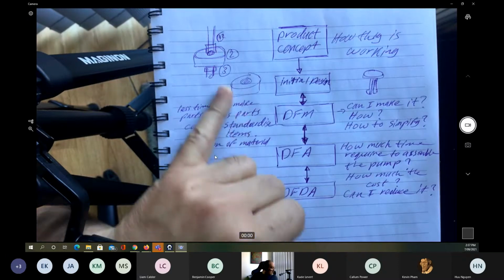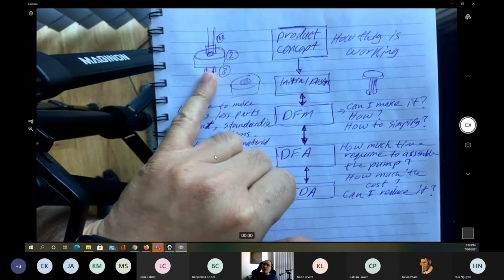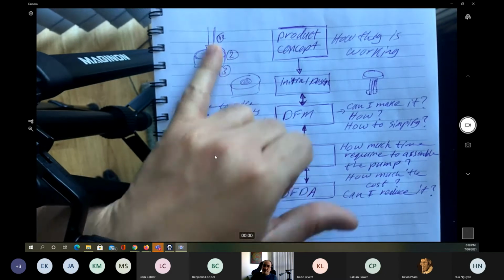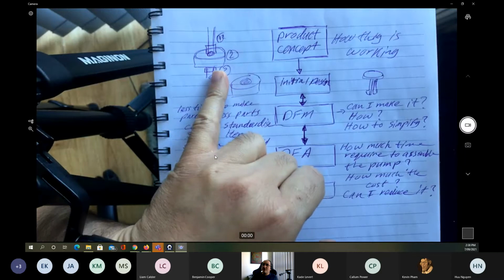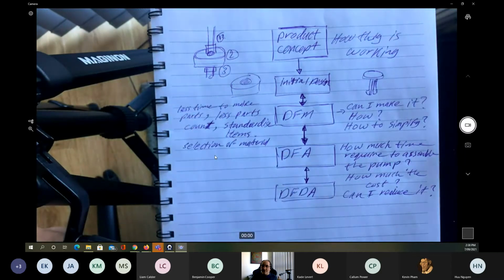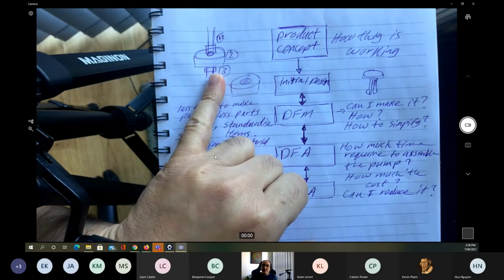For example, in this case, last time, a student used metal nuts, and the shaft is made of aluminum. They put it in the water for not more than 20 minutes. What happened is that the nuts got rusted. When I went to the lab last month, I tried to deassemble the valves. I couldn't open the nuts because they were rusty.